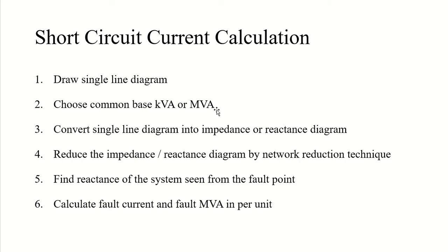Now, these were the assumptions. Now, what will happen in the case of fault? So, let's first talk about the reactance of generator, right? We normally take the reactances of generator as subtransient values. But if transient currents are also determined, then the transient reactances will be used.